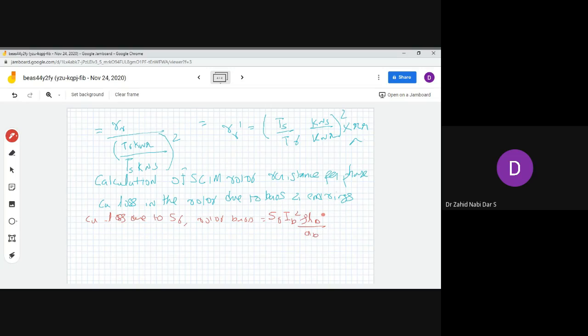So this would be the copper loss, and this copper loss is in watts. We also saw the resistance of each end ring, and the copper loss due to each end ring. If we go for the resistance of each end ring, the resistance would be rho times pi dE instead of L, since it's a circumference, pi dE, that is 2 pi r. You can write rho pi dE by AE ohms.